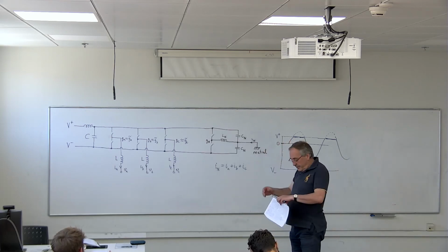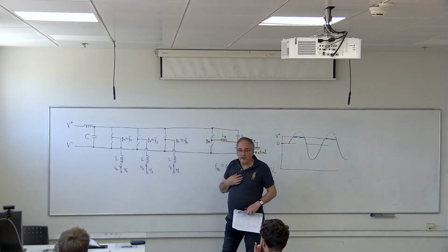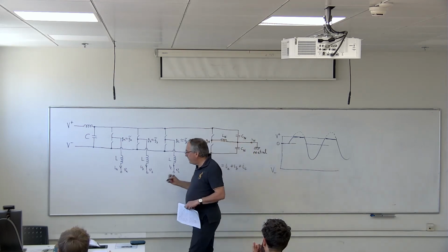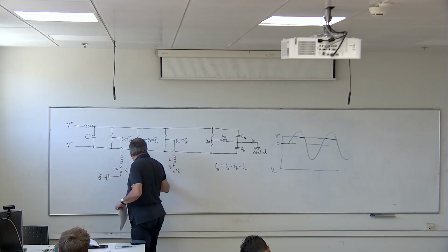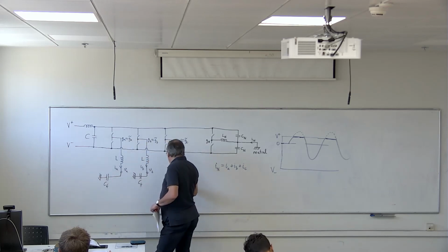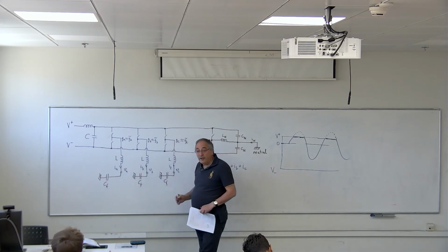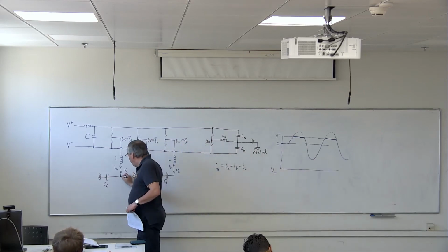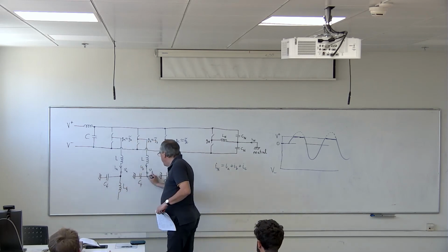What additional circuit may appear here? You see, one inductor on each phase does not have enough of a filtering effect. Usually, people put a filtering capacitor to ground on each phase. So this is CF, CF, CF. And then they put a second inductor. Not everybody does that, but if you want a good quality filtering, then you put a second filter inductor.